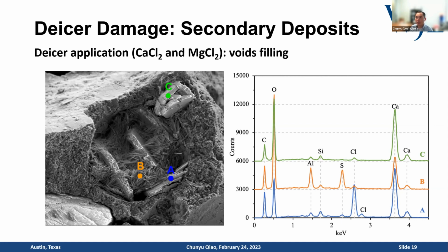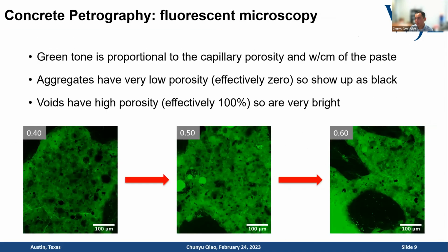So when I compare different water-cement ratios in those slides, I'm talking about mature concrete, after being well cured or in service for a long time. I just assume they have reached their maturity, their normal degree of hydration, at those water-cement ratios, so then you can compare. Again, if we look at the same water-cement ratio and different ages of hydration, from day 1 to day 7 to day 28, you will still see different porosity change, because your porosity evolves along with the water-cement ratio as hydration proceeds. So I don't know if I have explained it or not. Yeah, I think you did.